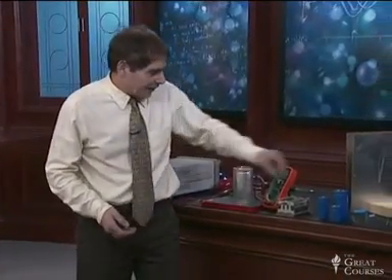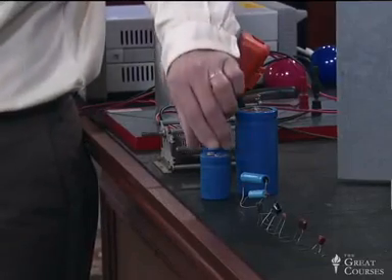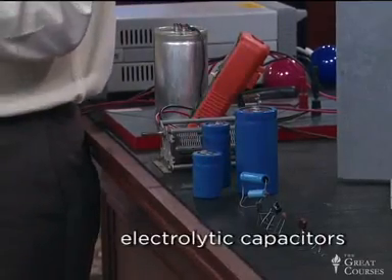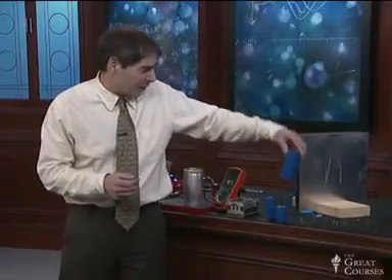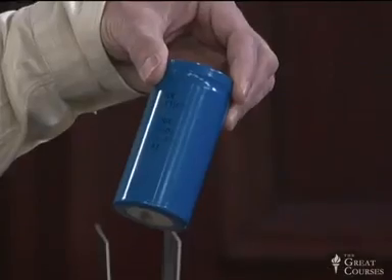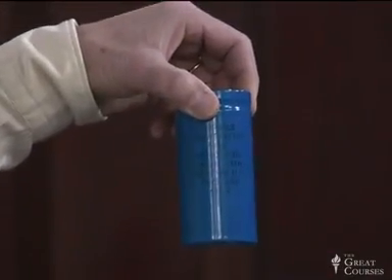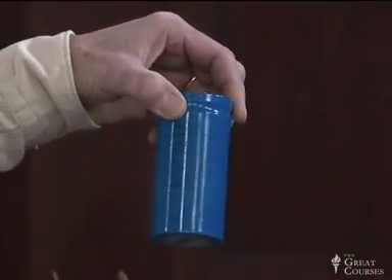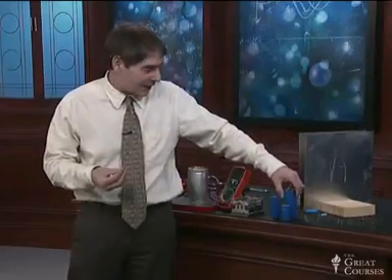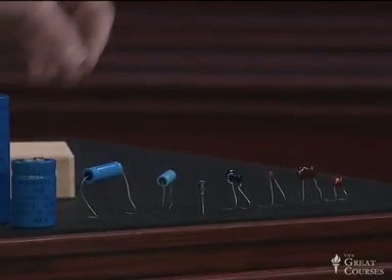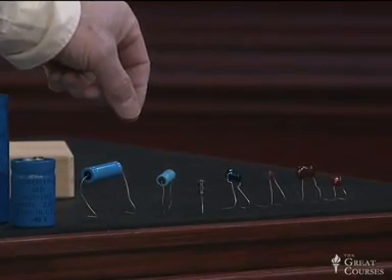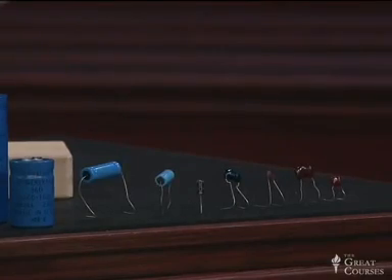So over here I have some examples of real capacitors. These are large capacitors that actually are called electrolytic capacitors, and the insulation is formed by chemistry that occurs when you apply a voltage across them. These have capacitances in the range, this is the biggest one, of about 18 millifarads, 18 thousandths of a farad. It's actually listed as 18,000 microfarads, but that's the same thing. And these are mostly decreasing in capacitance. That one's about 100 microfarads, about 10 microfarads. And the final ones down here have capacitances that are measured in picofarads, on the order of 10 to the minus 12 farads.